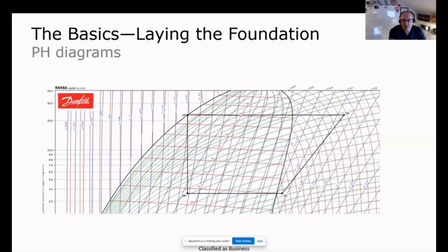So as we're talking about the vapor compression cycle, now this presentation wouldn't be complete without a slide showing a pH diagram. In very simple terms, the pressure enthalpy diagram, or pH diagram, shows how the pressure of a refrigerant, which is our fluid, changes when the heat, now that's the enthalpy, is given to the refrigerant or taken from the refrigerant. Enthalpy can be a very confusing concept, and basically I sort of think of enthalpy as energy or heat. The more heat you give to the refrigerant, the higher the enthalpy of that refrigerant.